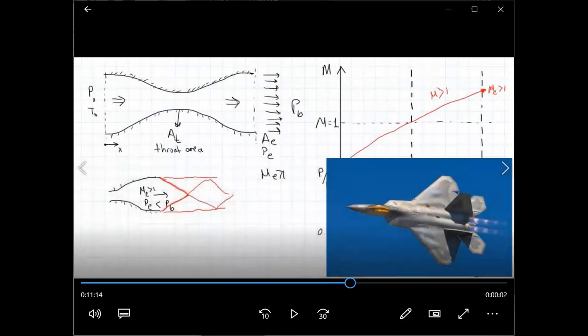And generally, for example, this happens when you're launching a rocket from sea level. At sea level, of course, environmental pressure is very high. So generally, nozzles operate in the overexpanded regime. If you watch videos of rockets launching from spaceports, and they generally launch from sea level, you can directly see from those videos the shock diamonds are generated. Those are just due to the oblique shock waves.